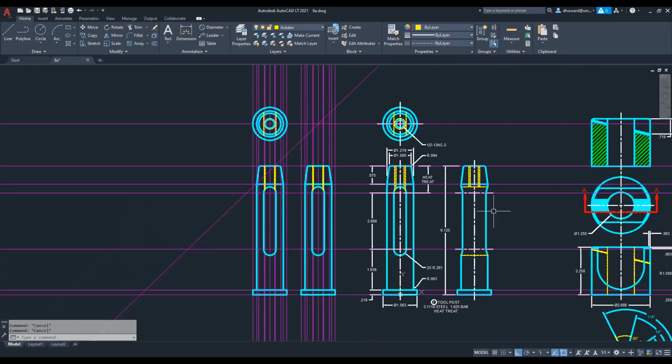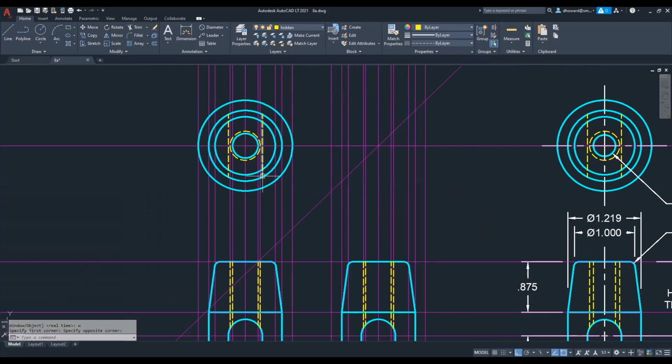But the other thing, as you can see in this example here, is that because we're looking at the slot from the side, it goes in. Okay. Let me zoom in on the top view. We get those distances from the edge here. And I'll make this stand out with a phantom line to really bring this home.